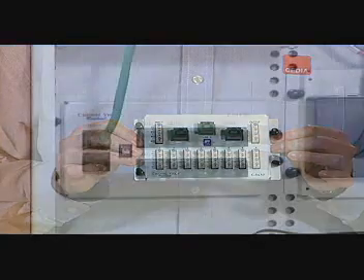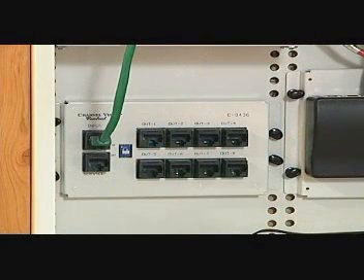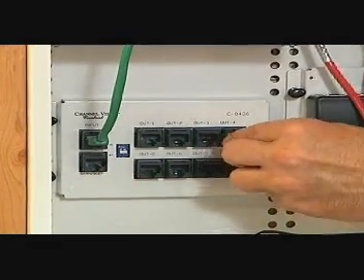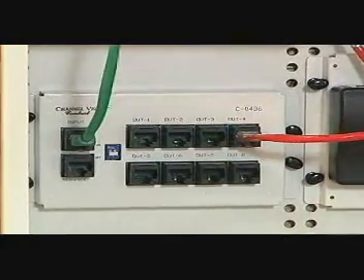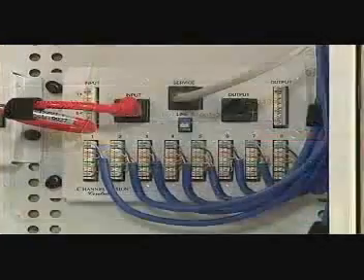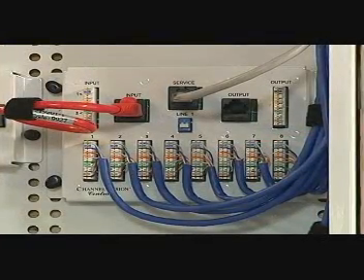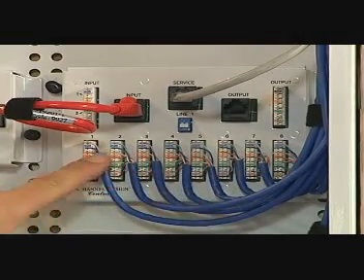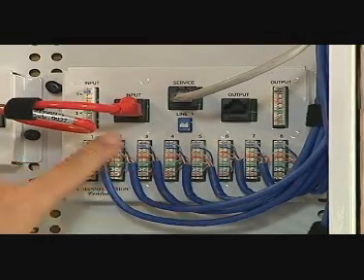or without a cross-connect. There are 2 methods used to terminate the TP cable runs to the module. The first terminates the cables in modular connectors. The cables then plug into the voice distribution module like this. The other method terminates each cable in a 110 style insulation displacement connector. The connectors are wired in parallel and connected to the incoming voice lines.